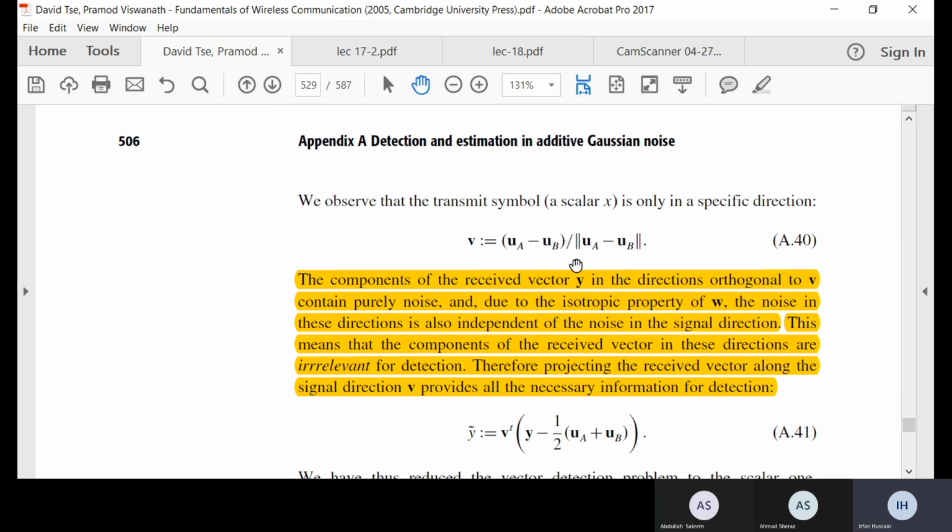We will be studying the rest also, but you can see that in all of our coherent modulation or coherent demodulation, when we were multiplying by H, we were finally converting our expressions to these UA minus UB expressions. They can only be achieved once we multiplied our input signal with these types of vectors. They are these V vectors in this direction, but in implementation, it comes out to be an H vector.